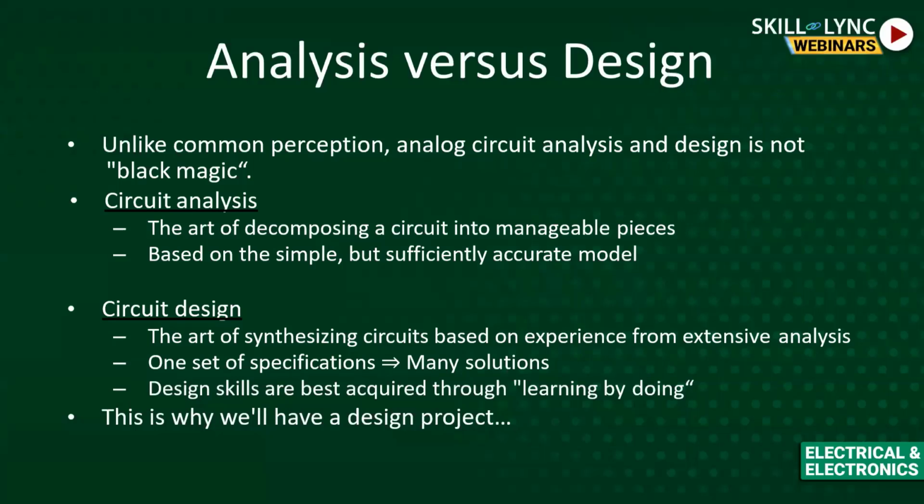Now, since I have brought up the word DC operating point, if you choose it correctly, your transistor will work as an amplifier, or if you choose it very low or very high, it will act as a non-linear device, basically just as a switch. That is what your digital circuits actually are. So this is what analysis and design is. I hope this is clear to you guys.